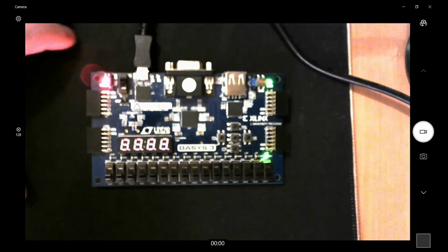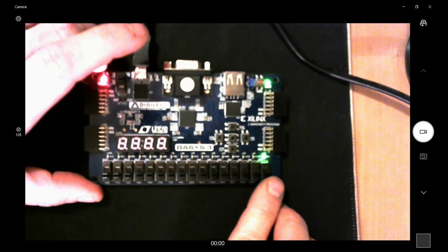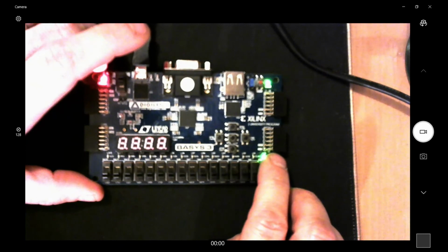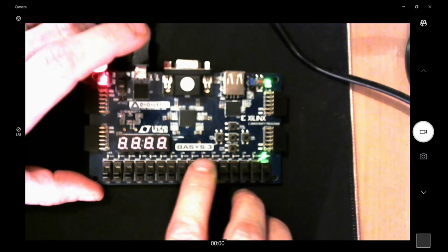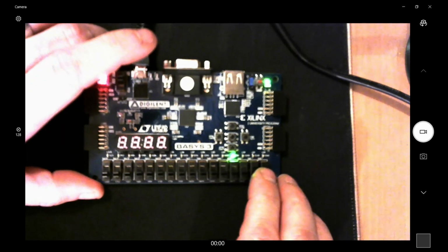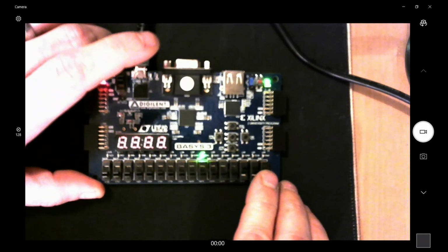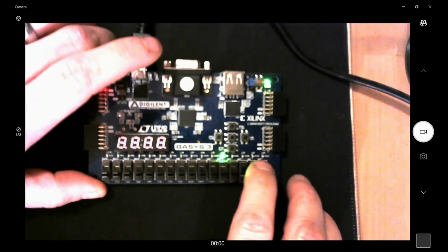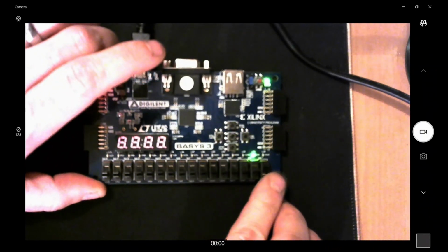Alright, here we are. We have the Basys 3, it's all programmed. You see it's got the lights on. Now we'll see the decoder. So these three switches are off, so we have essentially 0 coming in. So the LED 0 is lit. Now as I count up in binary in these switches, you'll see each corresponding light light up. So here's 1, 2, 3, 4, 5, 6, and 7. Now back down: 6, 5, 4, 3, 2, 1, and 0.